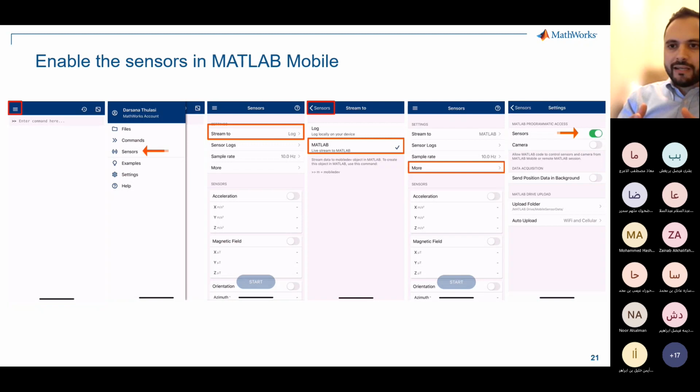Now, if you don't want this to be IoT, what you can do is send the data from the mobile into the MATLAB desktop directly. And then, because you are logging the data into MATLAB, you can go to the MATLAB desktop and you will find the live data being imported. MATLAB desktop can be connected with a cable to the Arduino, and the data will be jumping from your mobile into your laptop into the Arduino directly without going to the cloud of ThingSpeak. It will be going to the cloud of MATLAB, yes, the MATLAB drive, but it will not be public data to be shared with people like ThingSpeak with a dashboard.